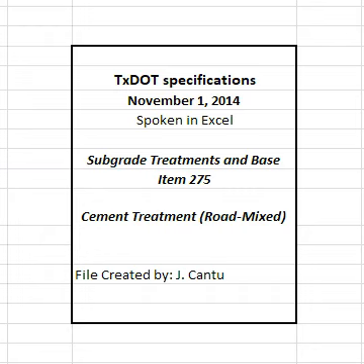The engineer may accept the section if no more than one of the 5 most recent density tests is below the specified density and the failing test is no more than 3 pcf below the specified density.